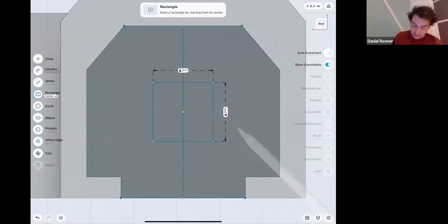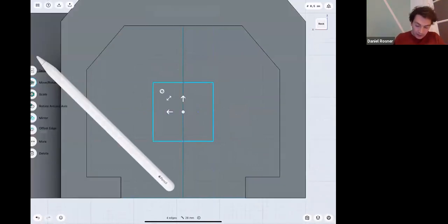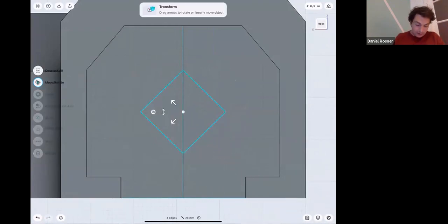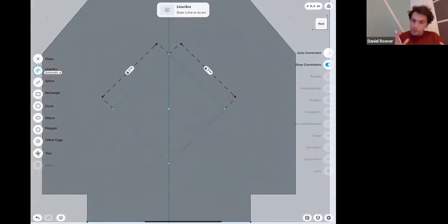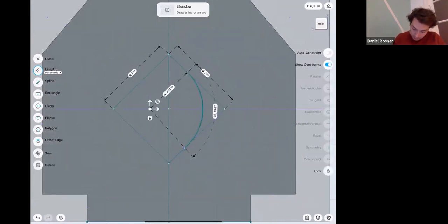Make sure it's 7 millimeters. Again, we are aiming for angled overhangs. So this rectangle might not cut it, but if I rotate it 45 degrees, that should be good. Great. What I also need is a small curvature on the side that eases the ball valve's path into this hole. So I'm going to create a small curvature here.